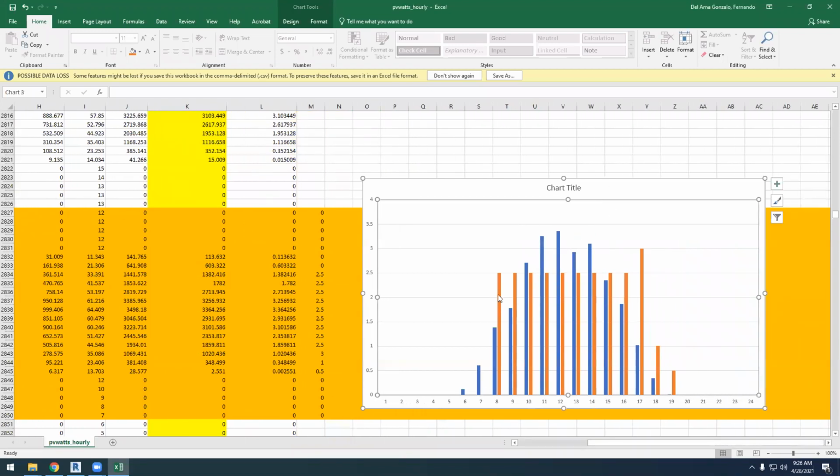And that's good because here we can understand whether we are having a zero energy building or not, when we have to sell energy and when we have to buy energy. So when the production is higher than the consumption, we have to sell energy. But when the consumption is higher than the production, then we have to buy the energy from the grid. Okay, so I think even with using PV Watts, we can have all this information that we had with the PVF chart. And now I find that PV Watts is more intuitive.